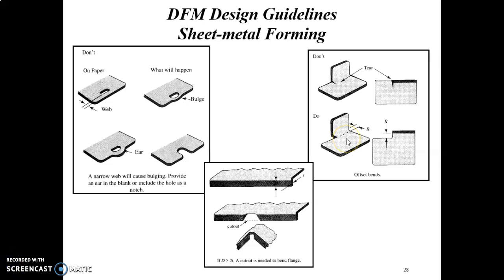This one illustrates a possible solution by changing the blank profile to provide a relief for the bend. Besides eliminating the chance of fatigue under stress, there is also a possibility of using stock 90 degree V punches and dies. So the results are better quality and less expensive engineering charges.